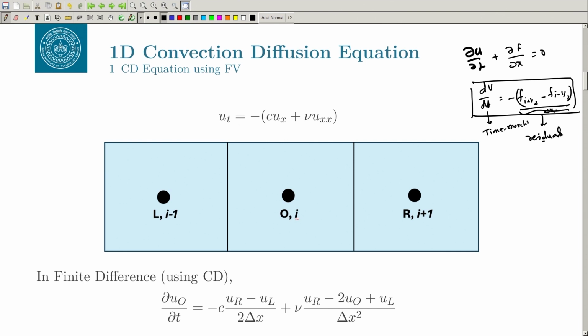Okay. So, we have discussed the nuances of the finite volume scheme, how to get the values of f at i plus half and f at i minus half. You will have cell centers on the left and right. Let us say this is i and this is i plus 1, so this will be i plus half. How do you get the value from the left and from the right, which one should you choose? And if you choose both of them, then how do you get the unique value here?